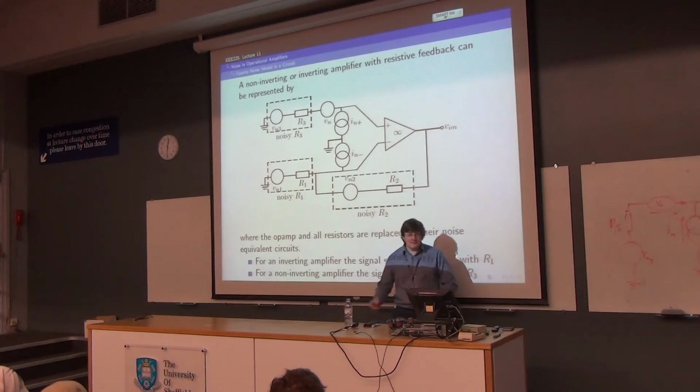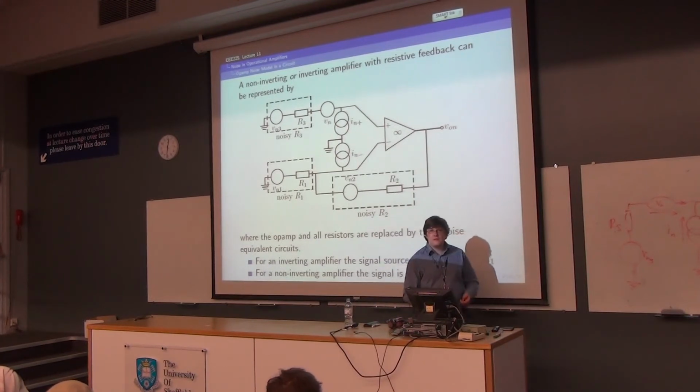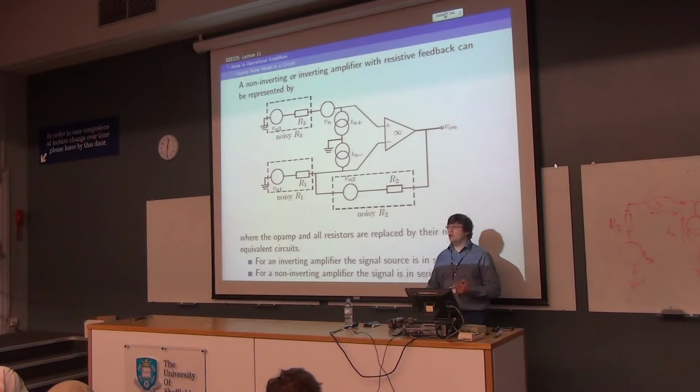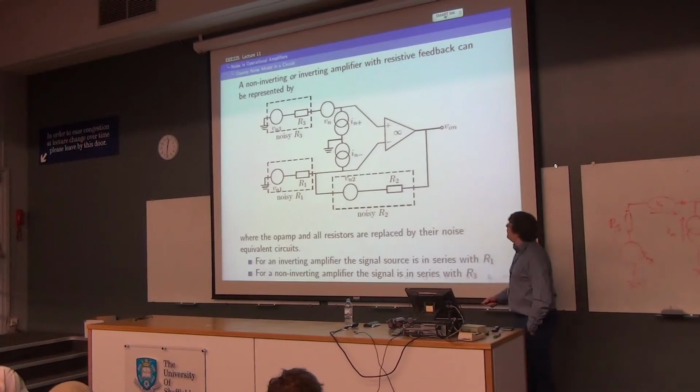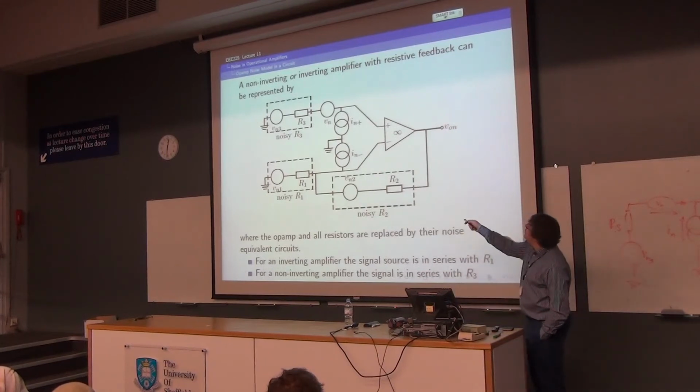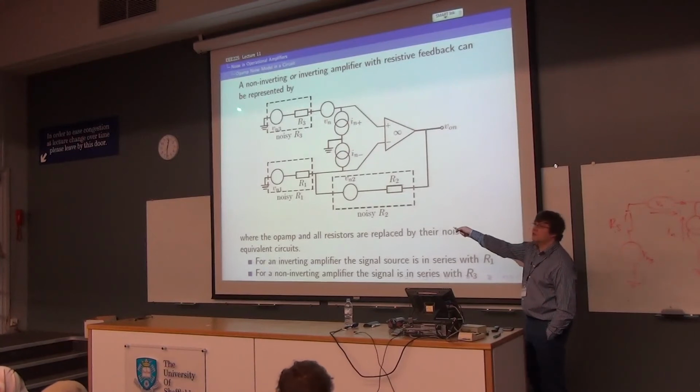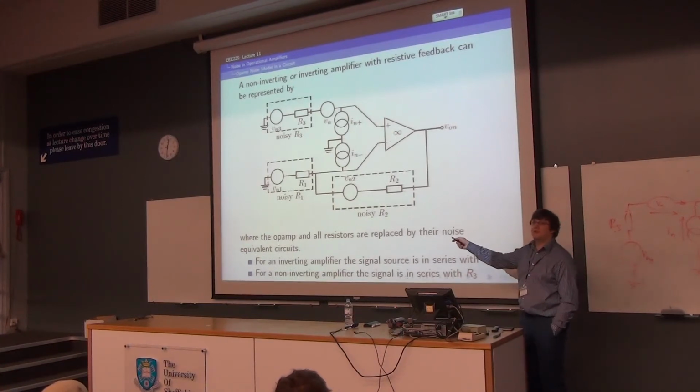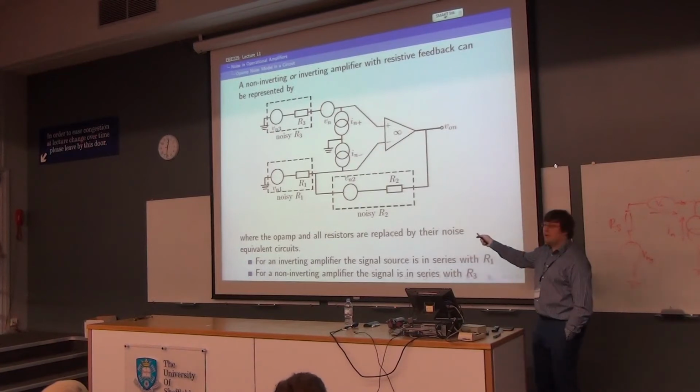So let's imagine that I wanted to make either an inverting or a non-inverting amplifier. Let's start with the non-inverting. R3 doesn't really play a part, because generally speaking you connect your source to here, and then your gain will be set by these two, R2 plus R1 over R2, yeah, that one.